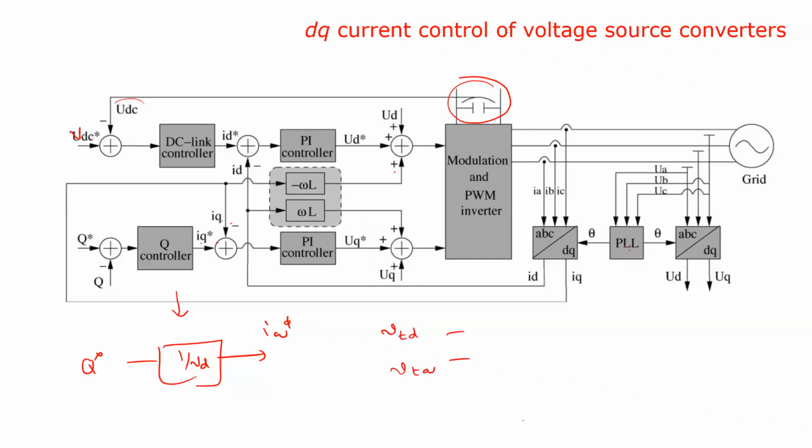So here, when you are using a sine PWM technique, the carriers range from +1 to -1, right? So you need to normalize this. These values are at full voltage, and the carrier comparison is from +1 to -1, right? So we need to normalize this one. After obtaining this, either we need to divide by the VDC voltage or by half of the DC voltage, VDC by 2. Okay, so that gives you the normalization, so that the modulating signals now range from +1 to -1 only.